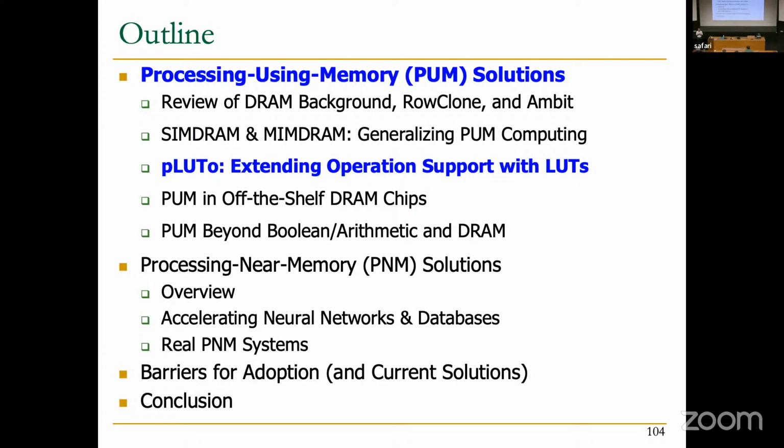Yes, I think it's also interesting to take into consideration whether you implement the coherency part in the memory controller or in the DRAM itself. If you implement it in the controller, you will need to modify the controller itself. And for the DRAM itself, it will introduce relatively high latency. Yes, and it's interesting.